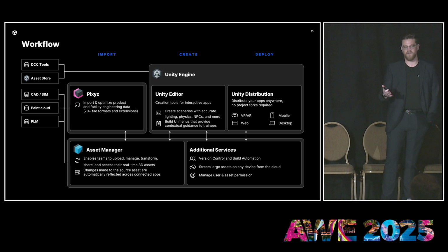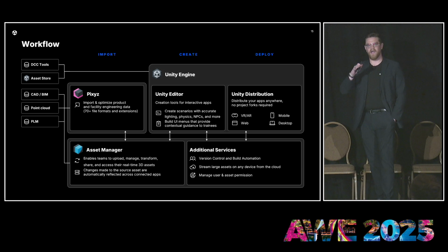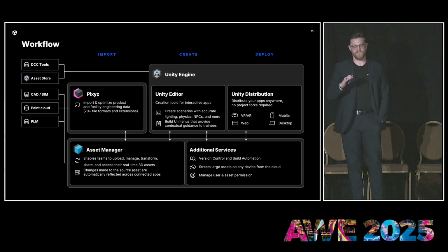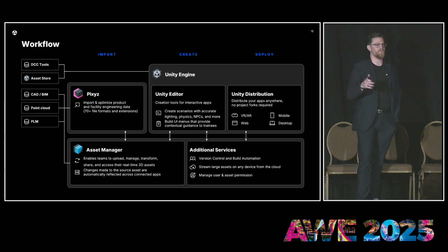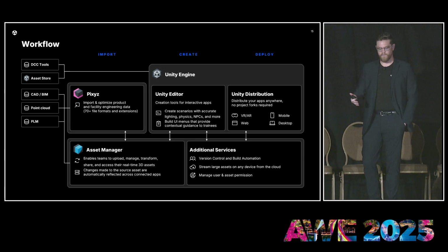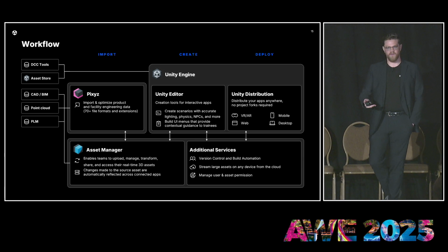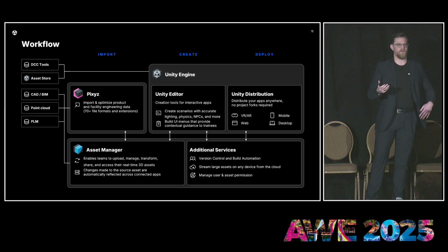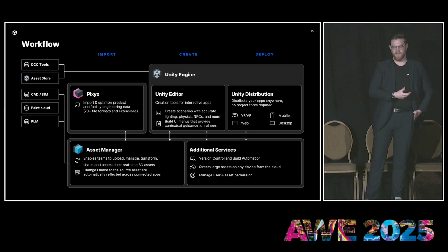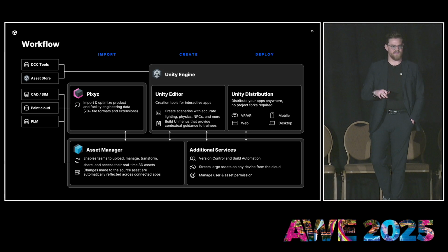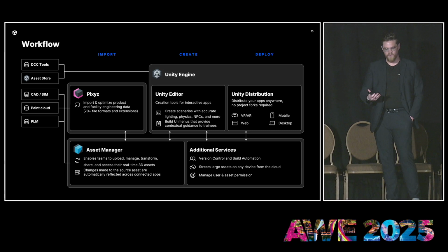And that process here can be kind of an either-or situation, if that makes sense. You can go straight into Pixyz, and use something like Pixyz Studio or Pixyz SDK to optimize those models, then push them out to Asset Manager where you can manage those. Or you can go directly into Asset Manager if you need more of a high-level look at the transformation workflow, and you can leverage the pieces of Pixyz that Asset Manager has built into it.